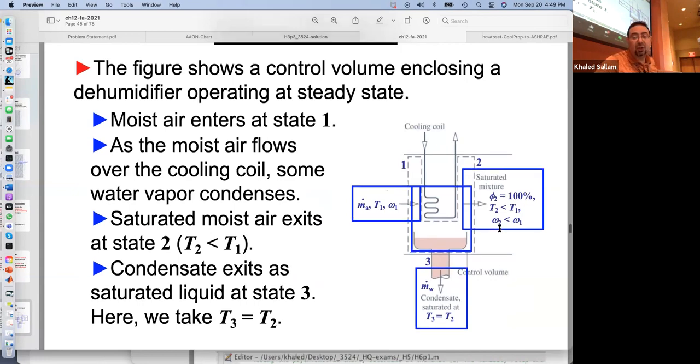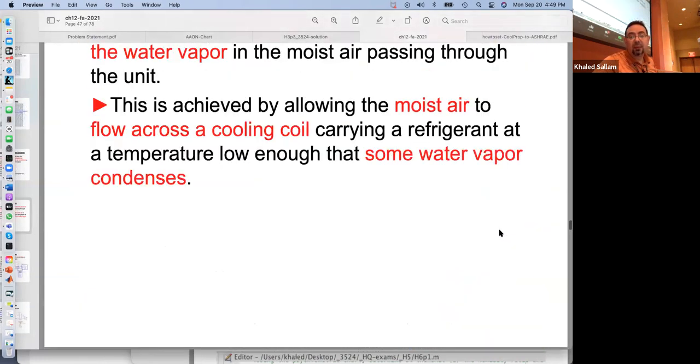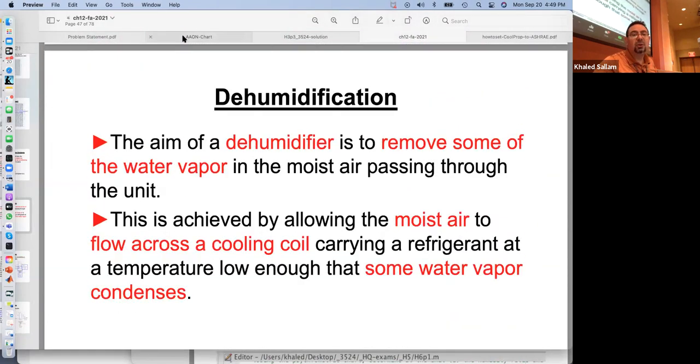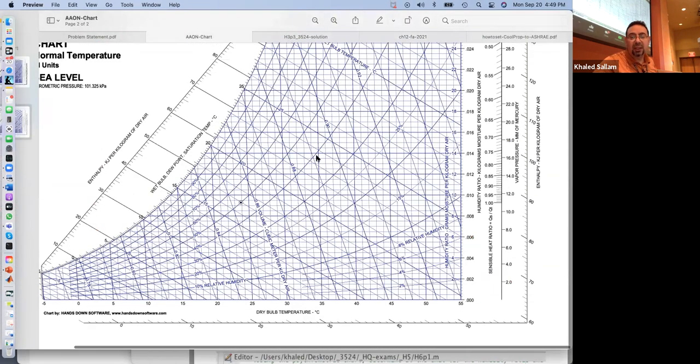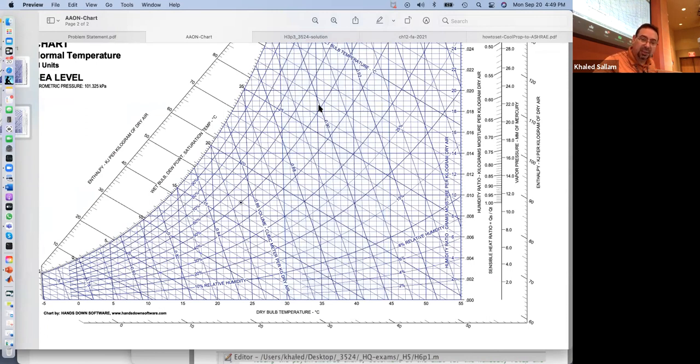Because in the psychrometric chart, what will happen? I have my psychrometric chart. Yes, here. So let's say that I am here at T1, 35 degree, and let's even go up a little bit. Maybe here, what is that? 60%? No, that's 50. 60% would be here. So 35 degree and 60%. Okay. So if that cooling coil takes me down to 30 or 25.